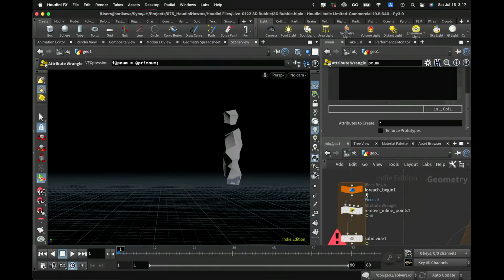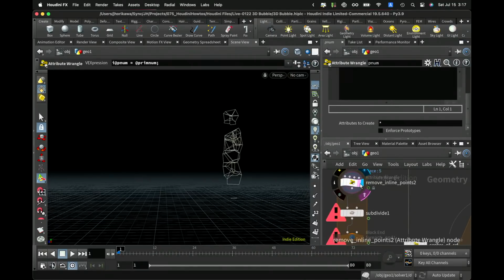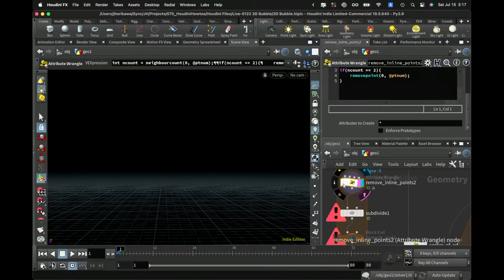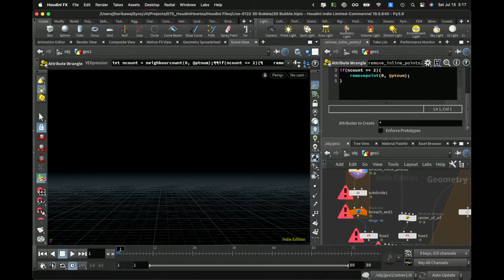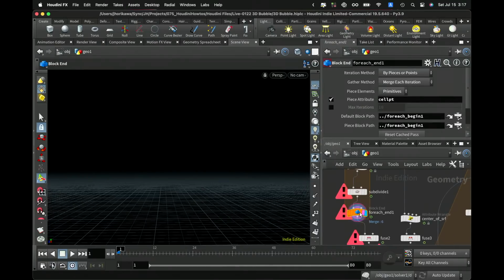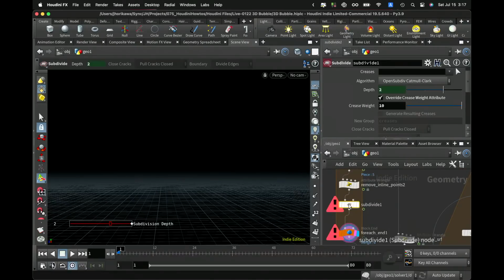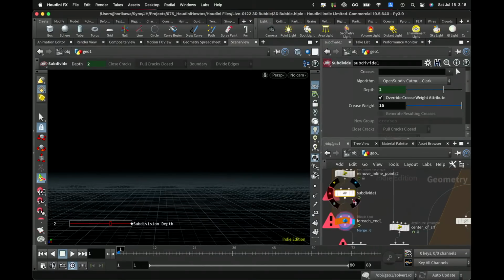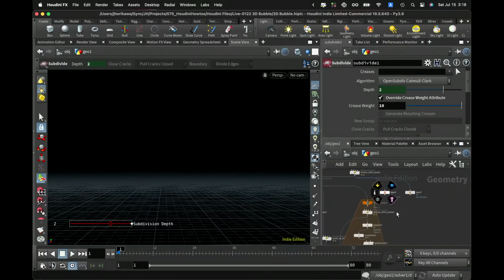The reason why I'm getting here is because some of the processes are making unsubdividable surface. So that's why. So maybe I could either create an error passing function, if one of the primitives is not able to subdivide, then skip that geometry, or just try to increase the number of points so that you don't get errored surface.